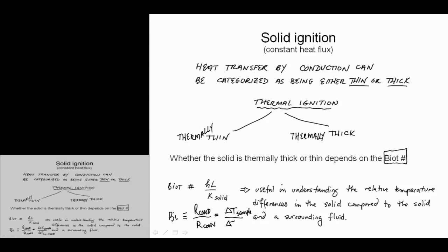Just to provide that diagram that we had before, we said, say this is the temperature on the inner surface of the sample, or the backside. There's a fluid over here at some T infinity. We said that there's a range of values of T sample surface that we might imagine to take place, and relative to, in some sense, this ground state of T infinity, the Biot number tells us which one of these we're sitting on.